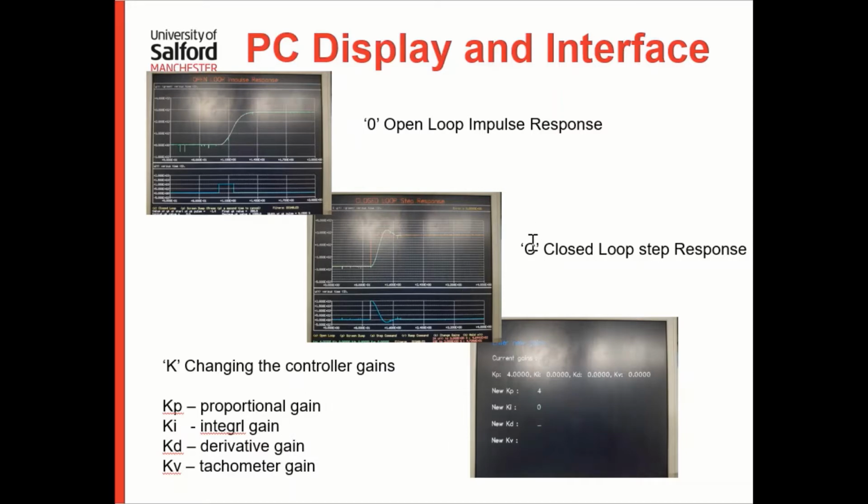So this is the test rig, and next thing we're going to do is move on to work out how to use the impulse response to obtain a transfer function of our DC servo. So this can be a handy method when you're designing control systems. If you've got a transfer function, you can then go into simulation, and you can use a simulation to work out good ballpark numbers for your controller gains. Otherwise, you're going to have to guess them, and guessing can be a bit dodgy.